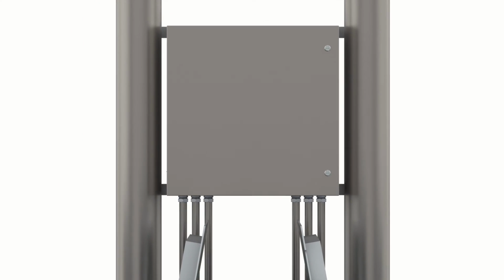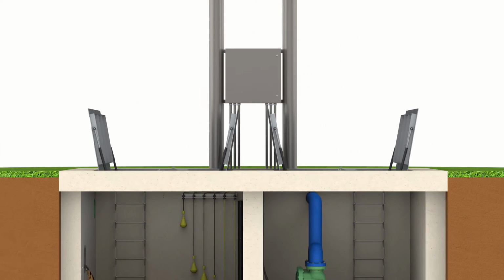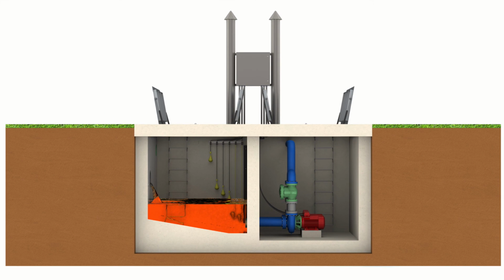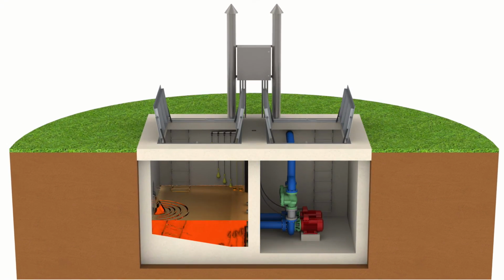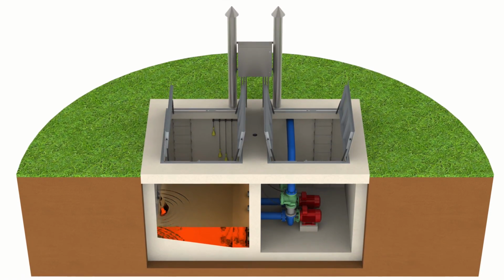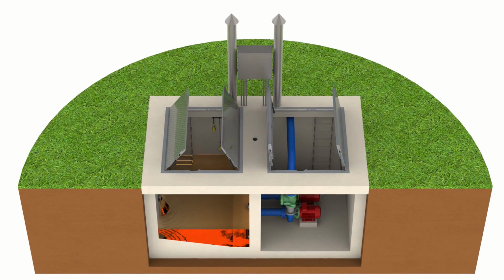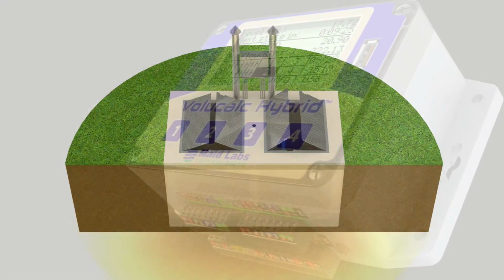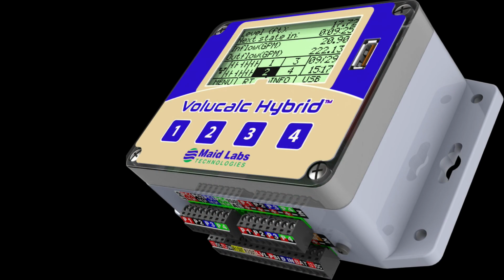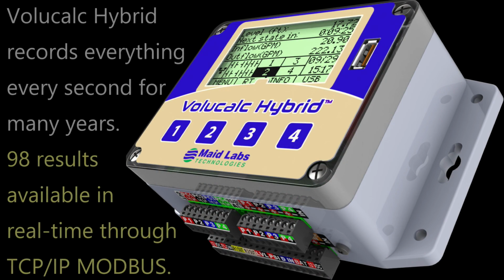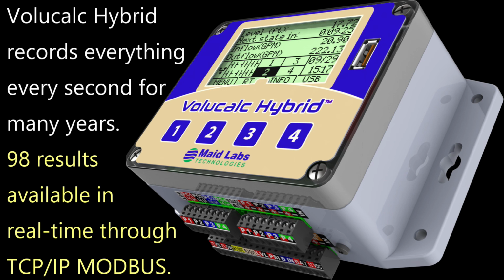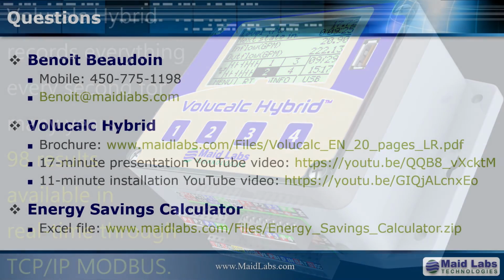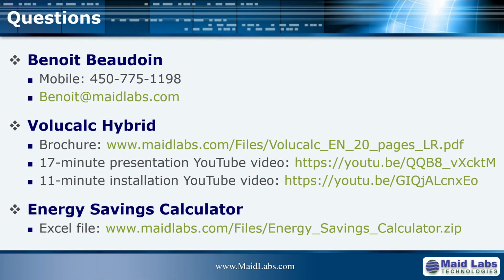As you might have noticed, there are different ways of installing this instrument inside a control panel. When you have a lot of lift stations and you don't have a lot of budget, I strongly suggest that you use it in your toolbox and you move it around. If you have a good SCADA system, make sure that it's working properly by cross-checking what you're getting using a device like this one. If you don't have any SCADA system, this can be just the heart of it. It doesn't replace a controller or anything like this, but it monitors perfectly what's going on inside the lift station.